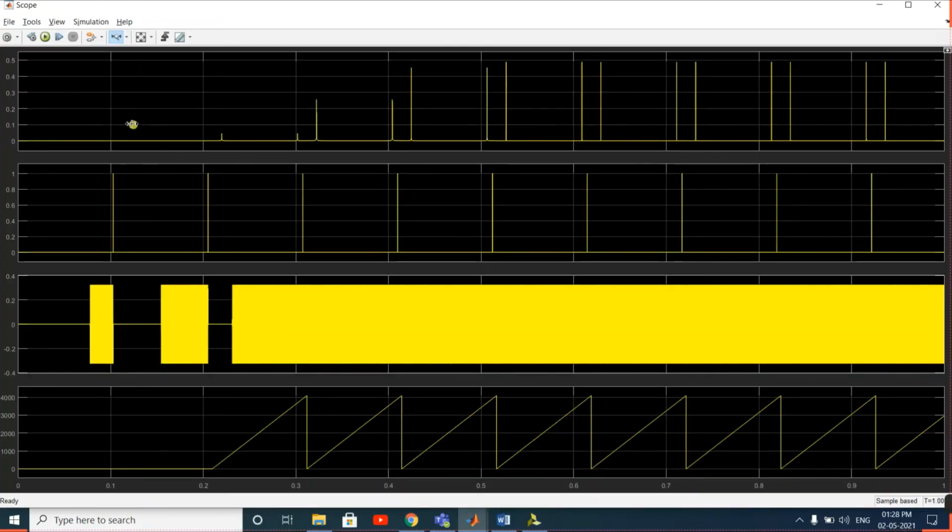Click on Autoscale X and Y axis. The first window displays magnitude output, the second window displays FFT last data arrived signal. The third window displays input data to the FFT core, ADC multiplied with Hanning coefficients. The fourth window displays frequency bin index. Any window can be zoomed by using the Zoom tool.